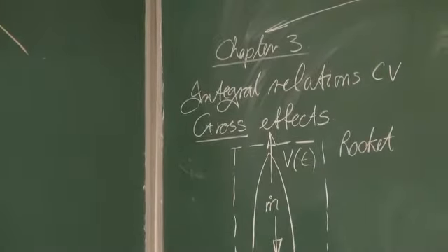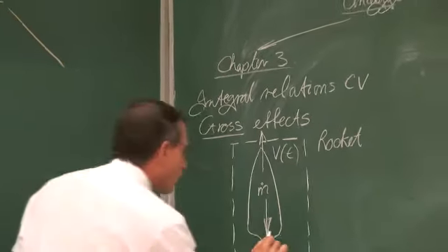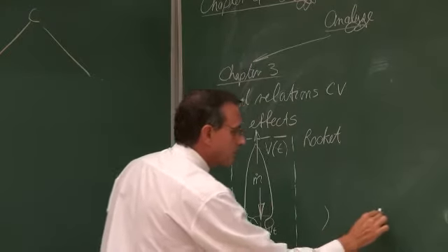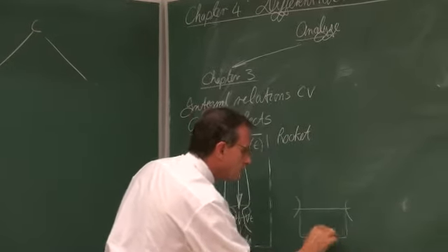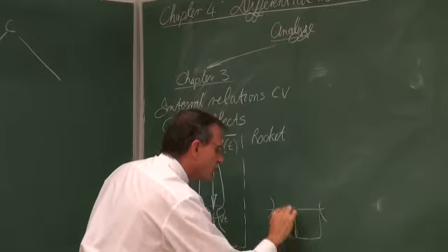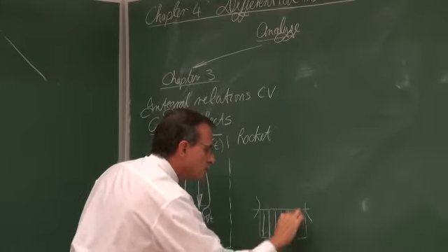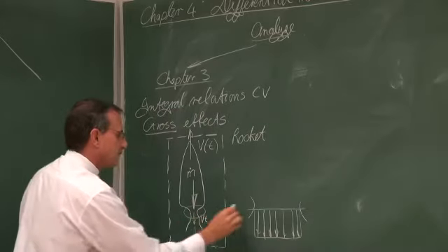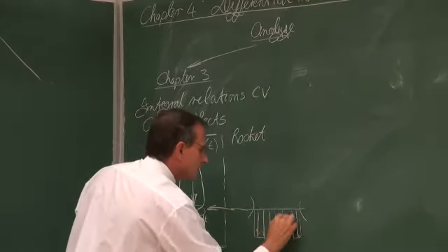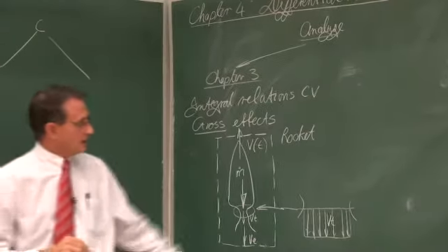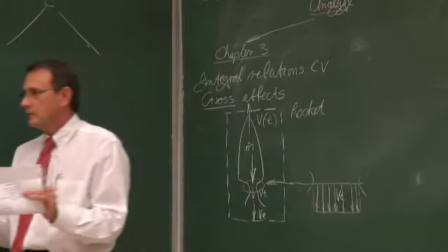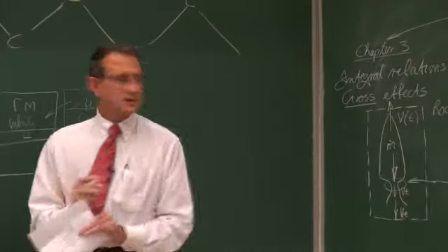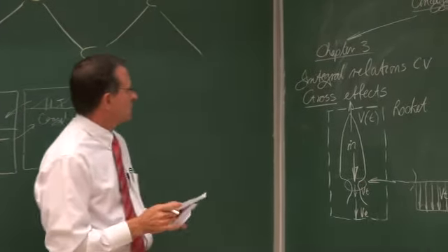Okay. And in most cases, what you did is you had a one-dimensional approach. So, for example, when you looked at that throat, the result of that assumption would be that if you solve the velocity, that the velocity would be uniform throughout that throat. So that would be the velocity at the throat. So the velocities are not equal to 0 on the walls. You're not interested in the details, just the gross effects. Okay, so that is what you did in that chapter.